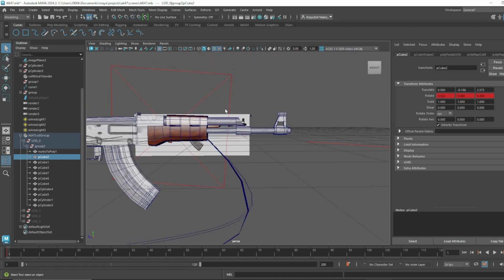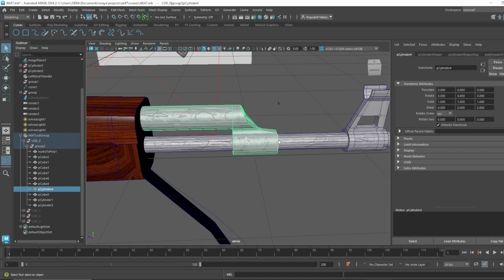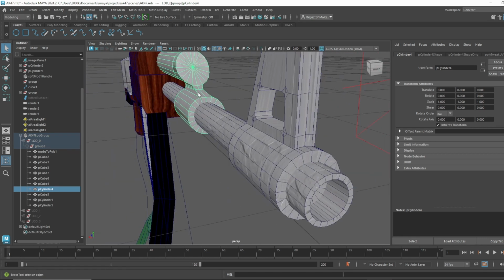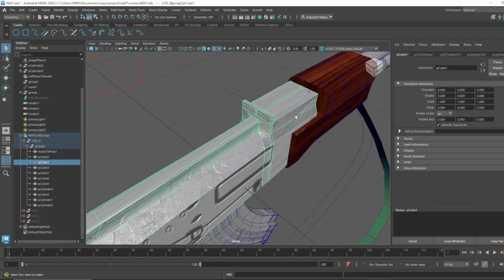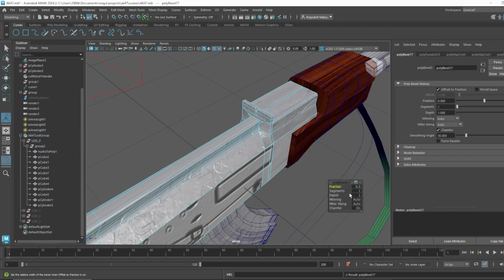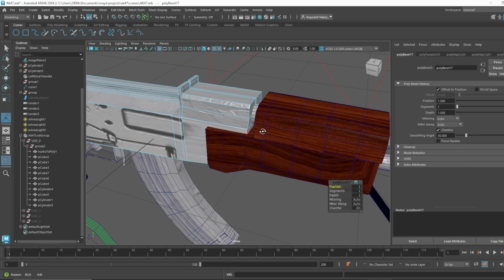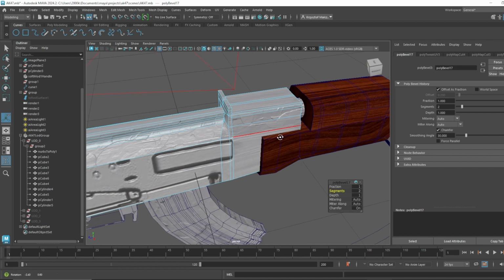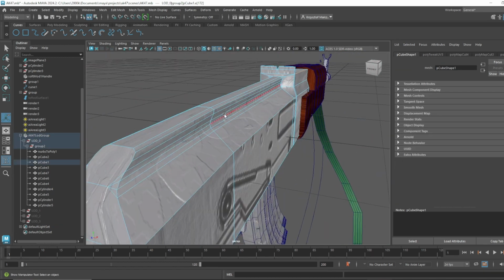And then with the barrels, this is for example a combination of two cylinders side by side, and I linked them together. Then I've smoothed out the edge, and the way I've smoothed out edges is pretty simple. I just select the edge itself, then I do Control F and I click bevel, and this produces this thing. So I can smooth out a certain edge whenever I need. I can add more segments to give it more resolution. This has been used, for example, here, where this smooth edge comes up.